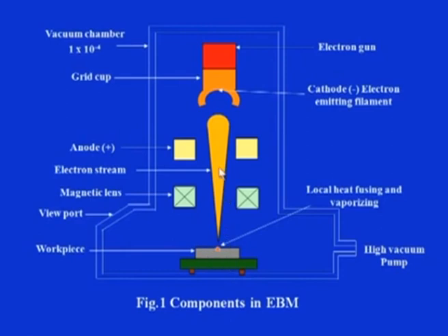Thus, because of the focusing of this highly accelerated electron beam, intense heat will be generated where the electrons strike the workpiece, and this workpiece will get melted.